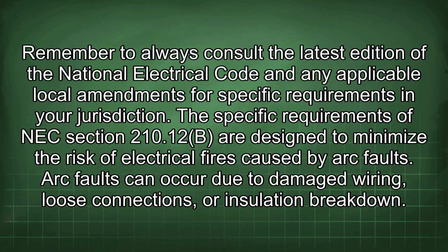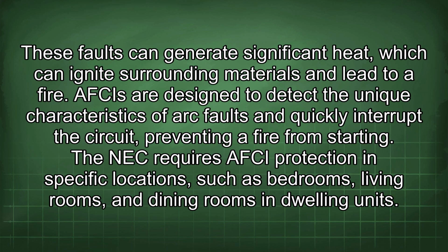Remember to always consult the latest edition of the National Electrical Code and any applicable local amendments for specific requirements in your jurisdiction. The specific requirements of NEC Section 210.12b are designed to minimize the risk of electrical fires caused by arc faults. Arc faults can occur due to damaged wiring, loose connections, or insulation breakdown. These faults can generate significant heat, which can ignite surrounding materials and lead to a fire.